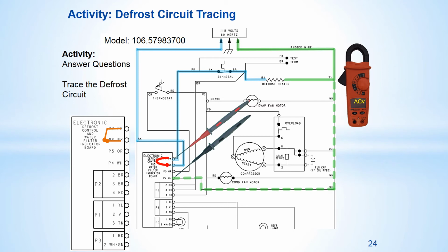This was done previously when the source voltage was tested, but just to be sure, relocate the red probe there and line voltage is measured. With 0 volts at P7 and line volts at P6, this indicates an open relay on the ADC board. However, you must ensure that the ADC is indeed in a defrost cycle in order for the relay to close. To recap, the open component will be indicated by the voltage going from 0 to line voltage as you walk the circuit from the line side of the load toward the source voltage.